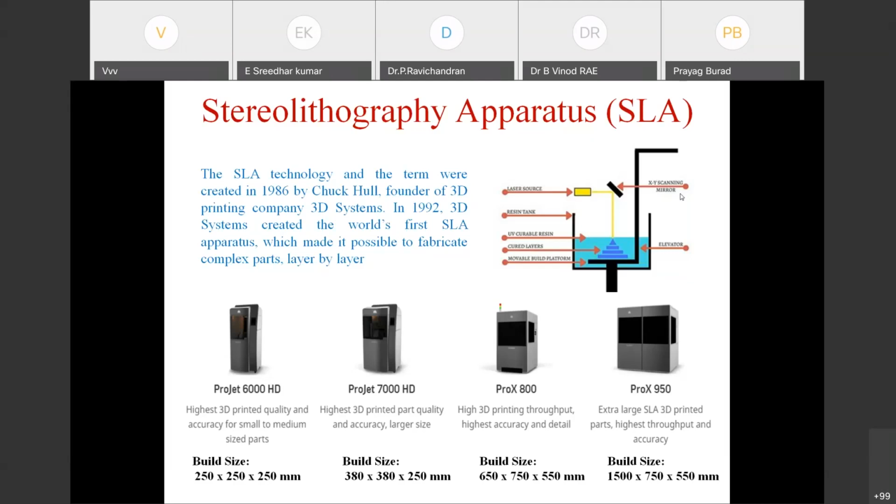Once the slicing is over, the CAD data is now in a sliced form. So the scanner will take the input from the CAD data layer by layer, and it will be scanned by the laser. Directly, the laser will scan over the raw material.